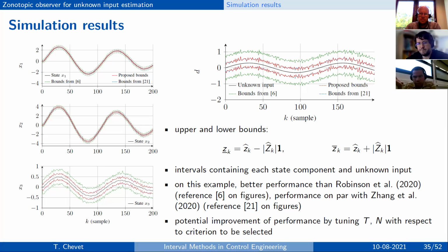And you use the zonotopic observer for the Kalman filter. He used the optimum based on the Frobenius norm, of course. It's not the best, but it's the optimum. So the next section, where you tune this parameter, doesn't make sense, because this is the optimum already with respect to zonotopic intersections.